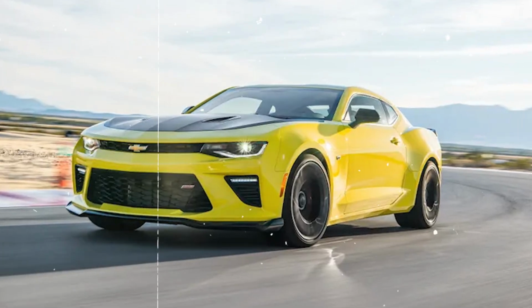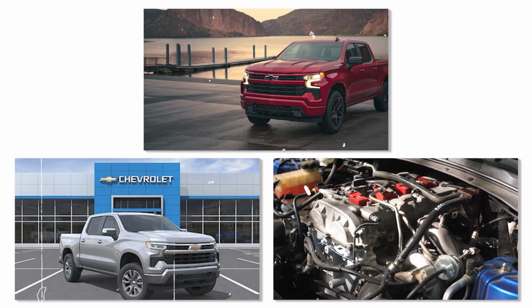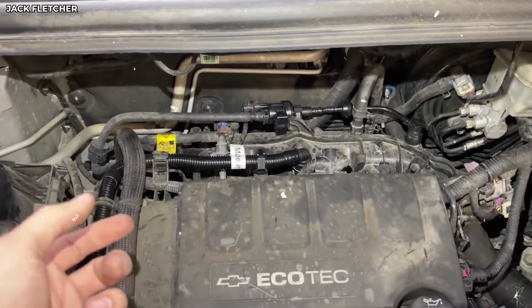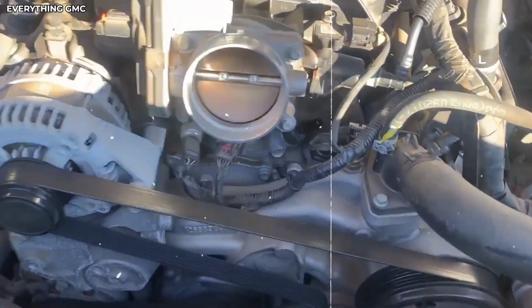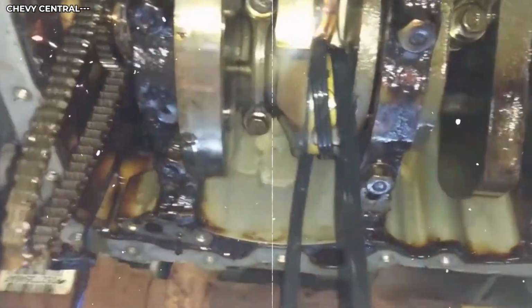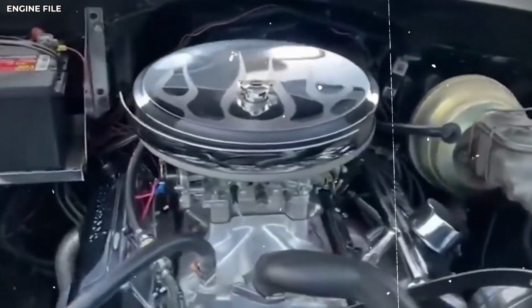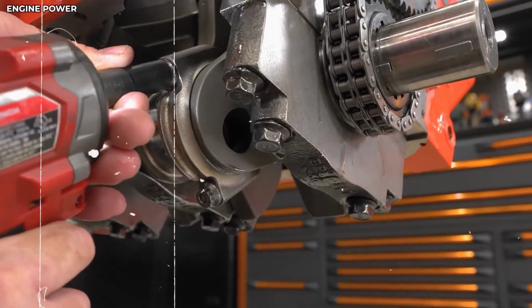Your throttle position learning system monitors the accelerator pedal position sensor constantly. This sensor reports a voltage signal corresponding to exactly how far you've pressed the pedal. 0% is completely released. 100% is floored. The ECU reads this signal and compares it against stored calibration tables that determine how much to open the throttle body. In a non-adaptive system, 50% pedal position always commands 50% throttle opening. But with adaptive learning active, the ECU modifies that relationship based on your driving history.